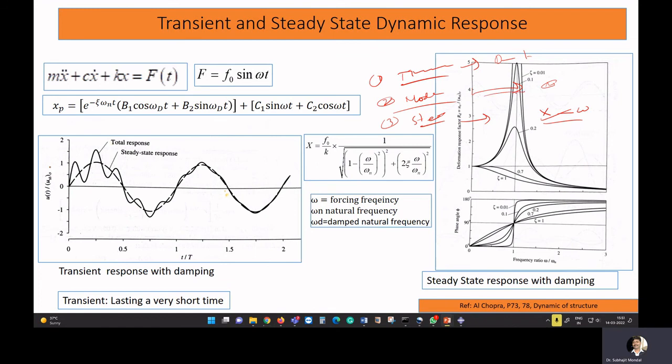And in the modal analysis, we observed that we can only find the frequency and the mode shapes. Here you can also observe that in the modal analysis we do not have any information about damping, because the equation we are solving for modal analysis does not include any damping. So we are getting real values of the eigen solutions, real frequencies and real mode shapes.